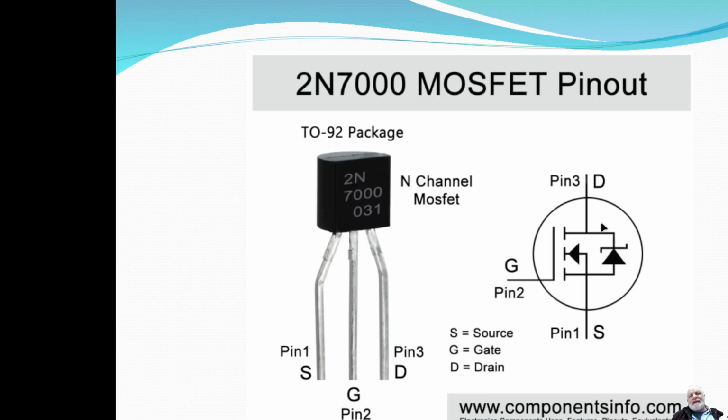In this case it's apparently a Zener diode, and what this does is it allows freewheeling access. If you have an inductive load like a relay or an electric motor that you're driving with this, it allows that inductance to dump its charge without destroying your device.